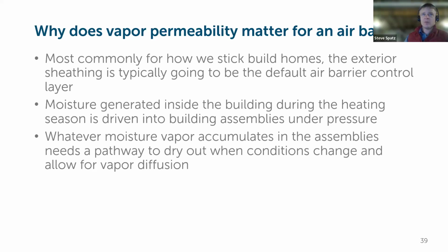So we're creating and generating a lot of moisture vapor within the building during the use of the building during the heating season. Managing that primarily with mechanical ventilation is the key defense mechanism. But as I've been saying throughout this, we can't stop these things from happening. We can't stop thermal conductive heat loss. We can't stop moisture vapor transport. We can slow it and we can control it to a certain extent.